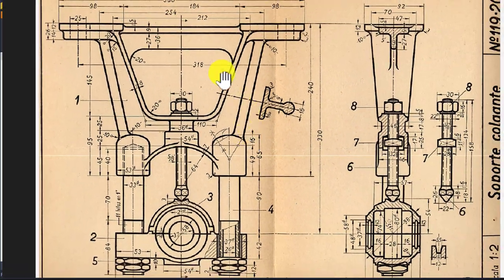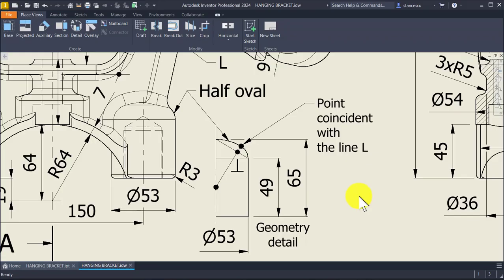And if we consider the section, we see that these two lines are ends for a cylindrical shape. We must consider the position of this point because we don't have any dimension to place these two lines at an angle. We have to use this point. This is why I made this special sketch to detail the geometry of the place.